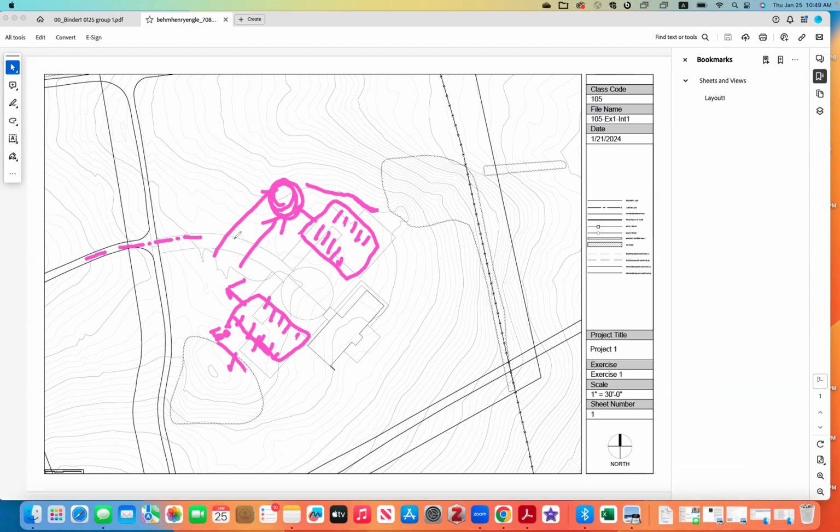It looks like you try to create a grand feeling once you get off the bus. And when people get off, you have a really little plaza for people to step on, right? So that doesn't align with your original design idea. It will be better if you have a more formal plaza space connecting the drop off, and also connecting this parking lot to your building. These walkways don't match the demand of the pedestrian flow from both of these parking areas.